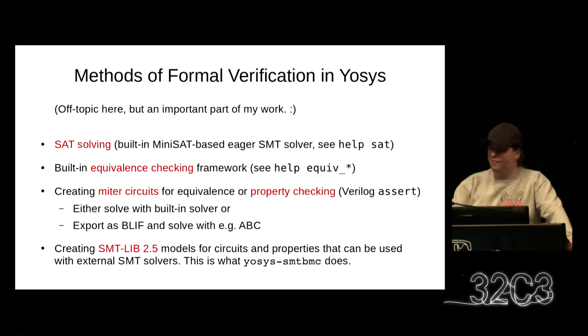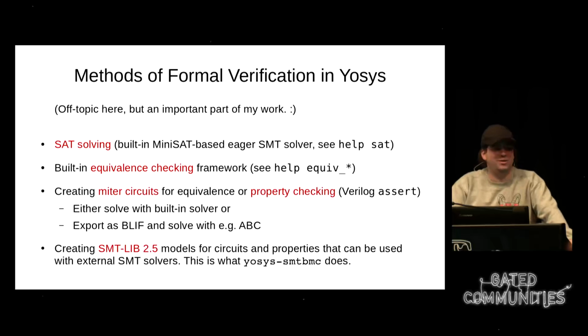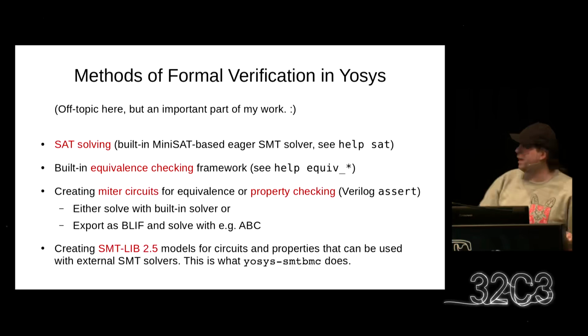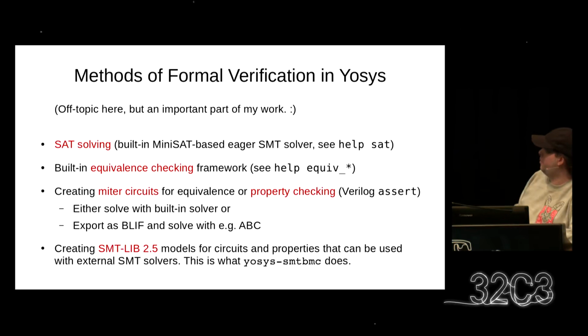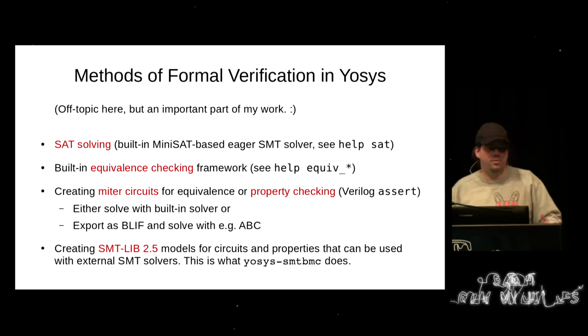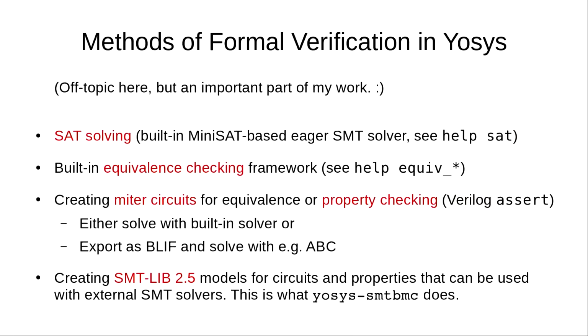As I've mentioned already, formal verification is something that is very important for me. So I had to have a slide here about different formal verification methods that can be used with Yosys. There is a built-in SAT solver that can be used to answer simple questions like, is there any sequence of n time steps where in the end the signal A is high and the signal B is low, and then it will try to find such a sequence.